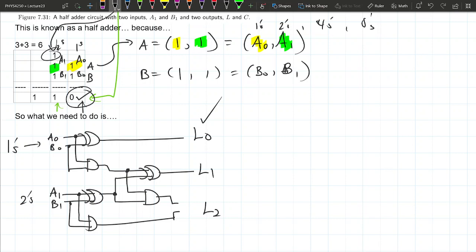So the AND between 1, 1 should be 1 as the output here. Let's put intermediate here. And then the XOR between 1 and 1 should be what? 0. So now these come together. The XOR between 1, 0 should give you what? Should give you 1. So this does work, at least in this case. And I'll let you check the other 15 cases, because there's actually 4 different combinations you can set up here. But it does work for our calculation right now.